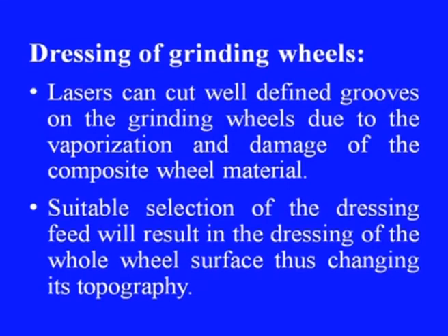Laser beam machining can also be used in dressing of grinding wheels, which is very effective. Lasers can cut well defined grooves on the grinding wheels due to the vaporization and damage of the composite wheel material. Suitable selection of dressing feed will result in dressing of the whole wheel surface, thus changing its topography. The multiple cracks which are induced thermally during laser dressing help to remove the resolidified layer during grinding, which then exposes new cutting edges.